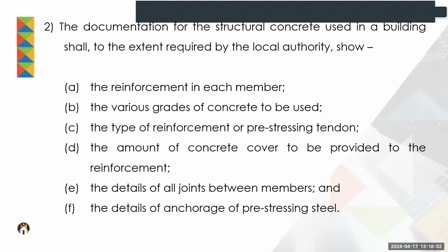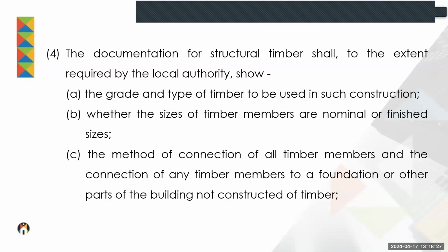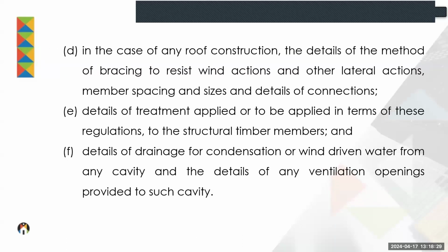But the regulations require that all other structural details, which are not required upfront, be submitted to the local authority at least 3 days before the work is executed on site, and then they will be deemed part of the approved set of drawings. As you can see, the different structural steelwork, structural timber, roof construction, etc.